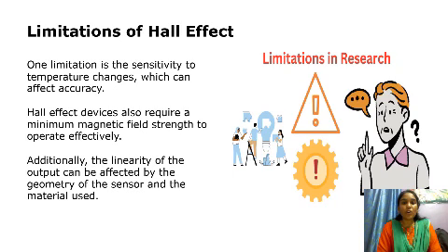Limitations of Hall effect. One limitation is the sensitivity to temperature changes, which can affect accuracy. Hall effect devices also require a minimum magnetic field strength to operate effectively. Additionally, the linearity of the output can be affected by the geometry of the sensor and the material used.